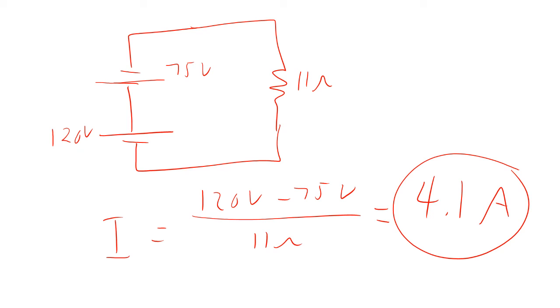Okay. And so what you notice is that under load, once it spins up, this is something that actually happens with a power tool: when you first plug it in, before the motor starts spinning, it takes a lot more current than it does once it spins up to full operating speed. Because once it's spun up to operating speed, you have the back EMF, which is actually slowing it down.